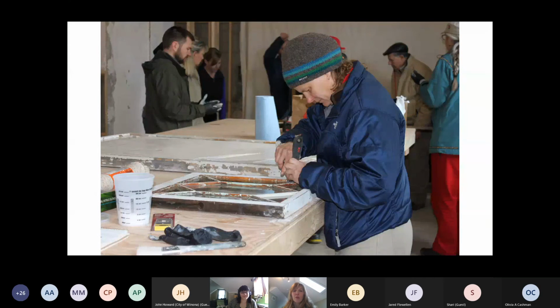One of our most popular classes is historic window repair. So this is one of those ways that, just on a very small scale, people can take a green step by rehabilitating and repurposing their historic windows and making sure that they function. We actually, in my household, just last weekend repaired the sash cords that had broken in the kitchen.